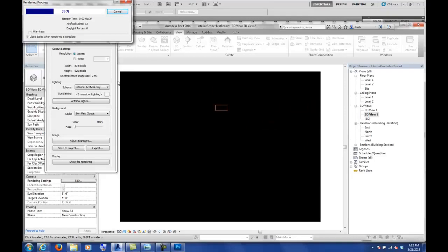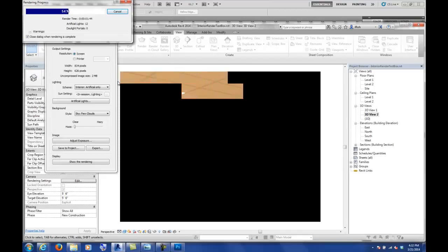This is taking a little bit longer than I expected, but essentially what that means is every time we make a new material, if you're ever going to make a tweak to it, I would say you definitely have to do this: duplicate the material, and we'll go over this as soon as this is done. You duplicate it, and then you make it a unique name so that when it goes to the cloud, Revit doesn't overwrite it. I found that out the hard way. It was horrible.